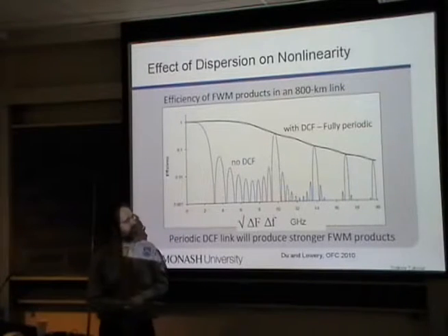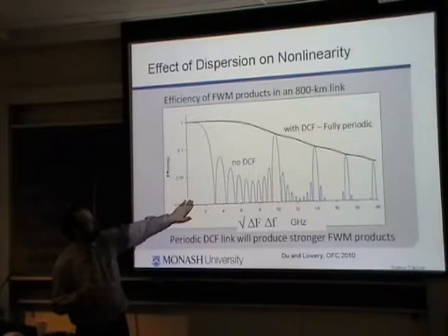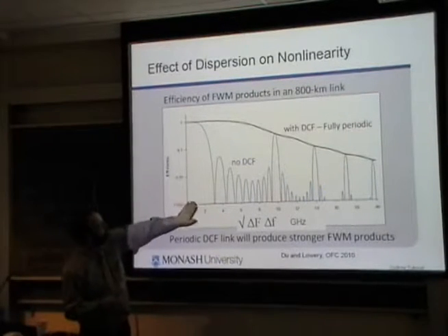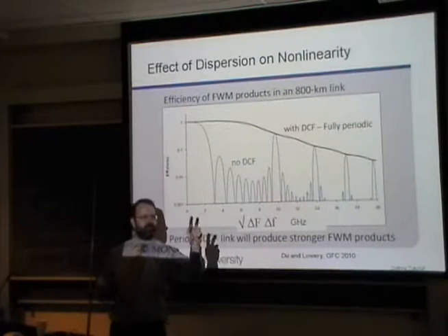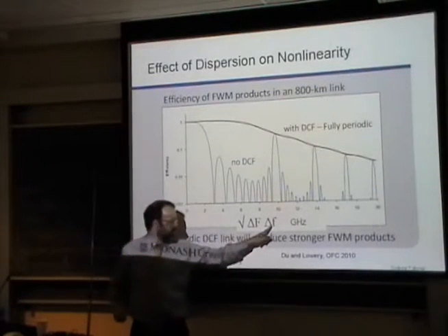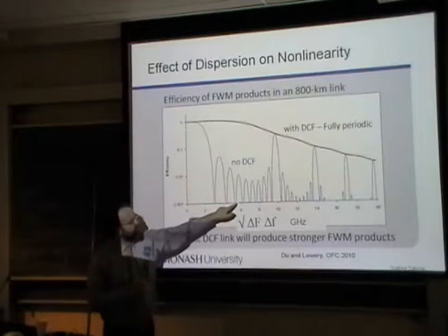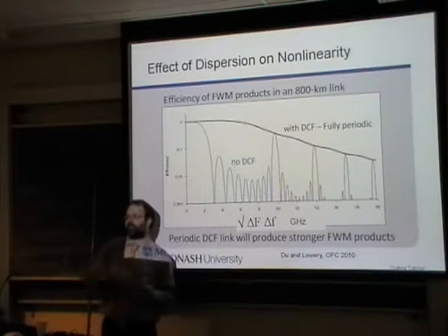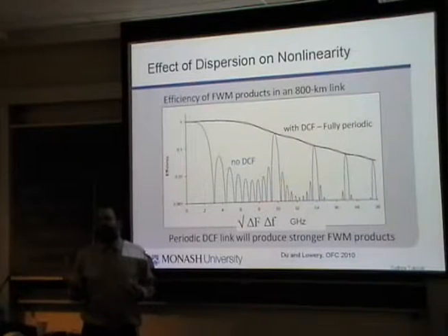And we get this graph called the four-wave mixing or cross-phase modulation efficiency graph, which says that the strength depends on the frequency separation between the 2 tones and the one that's being modulated and the 2 tones themselves. And where we get a null is where these individual spans of fiber have all added up to get back to the origin.